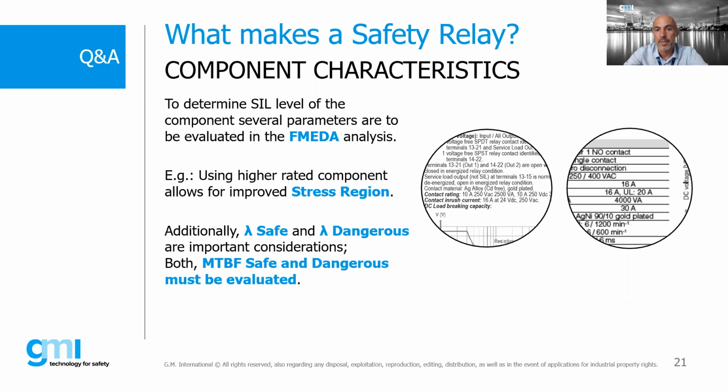All the components must have FMEDA values, FMEDA calculation supplied by our supplier. So you cannot use any single component you find in the market. If you want to have a SIL-rated product or SIL-rated relays, like in this case, the components must be, of course, safe.